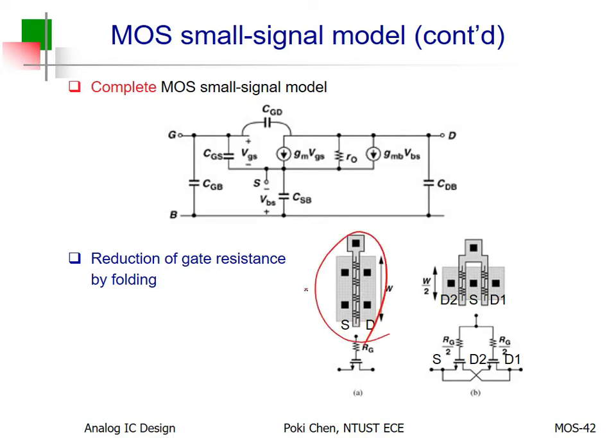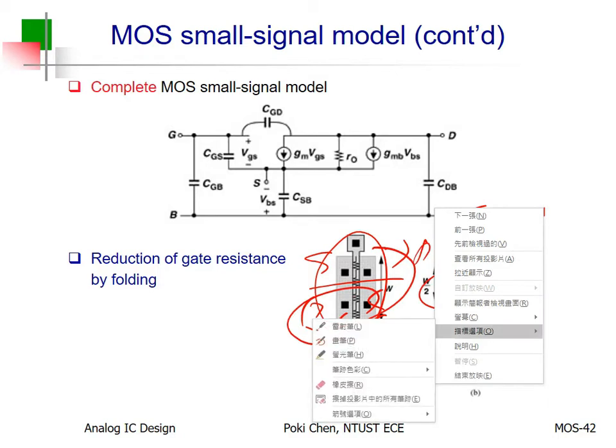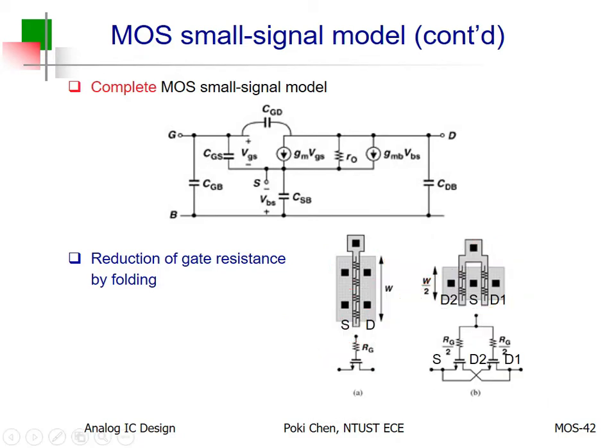Yet again, this is what I showed you. Yeah, you split it, source, drain, and then change drain to source. Then they can be overlapped. Drain, source, source, as you like, I don't care. Not only will the parasitic capacitance be reduced, but also, you can see, for the gate, polysilicon is no good for conduction. Okay?